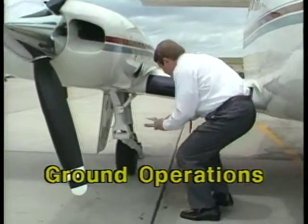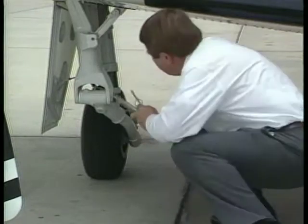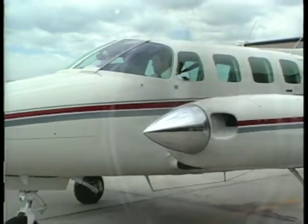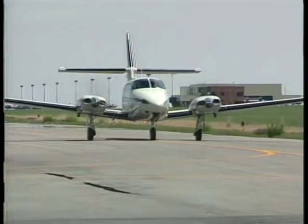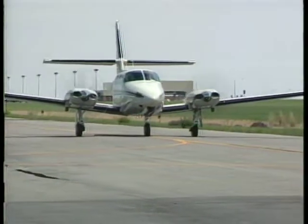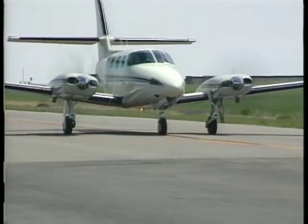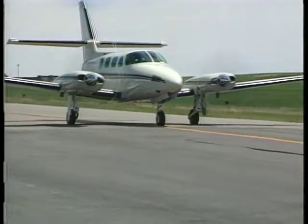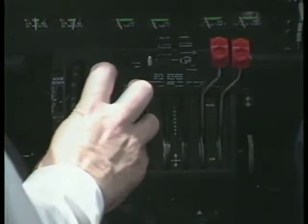The complexity of multi-engine airplanes makes it imperative that you use the proper checklist for all ground and flight operations. When you're ready to start the engines, clear the area around both propellers as well as around the entire airplane. Some aircraft specify which engine is to be started first, while in others there is no difference. With two engines, you have several options to help maintain directional control while taxiing. In most cases, nose wheel steering is sufficient for normal operations. But if you need to make a tighter turn, you can use differential power. This is accomplished by increased thrust on the outside engine.